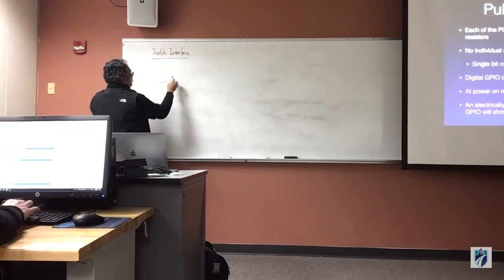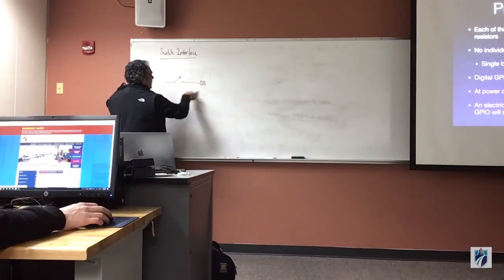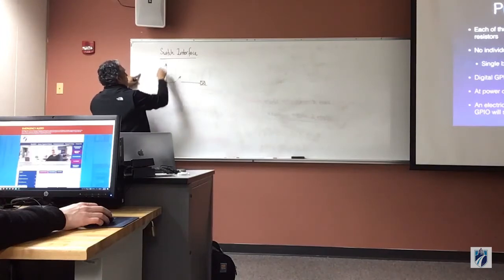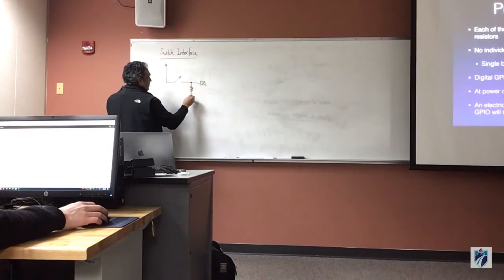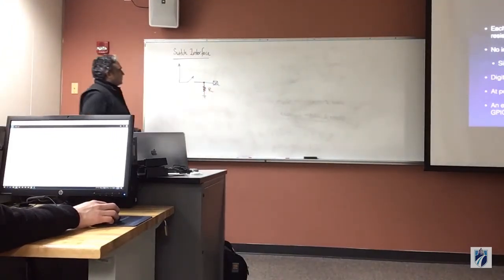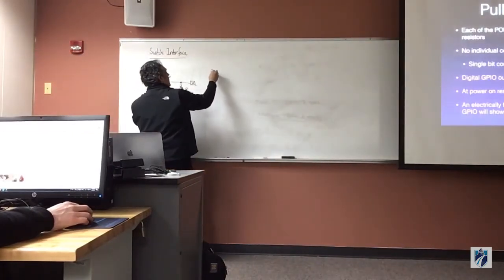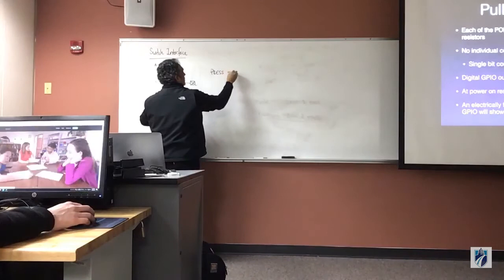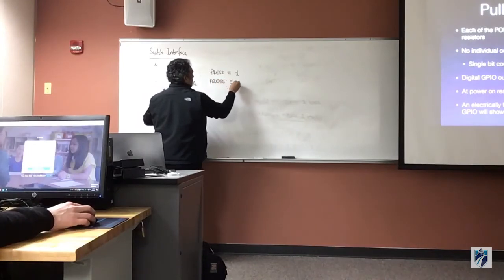We got a switch, a connection to the micro. So I'm going to put here the little micro connection, right? And then we got power in one end, and then we got a pull down resistor on the other, like so. Right? And this gives me a press with a logical 1, and then a release gives me a logical 0, right?